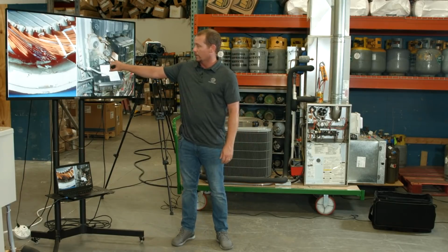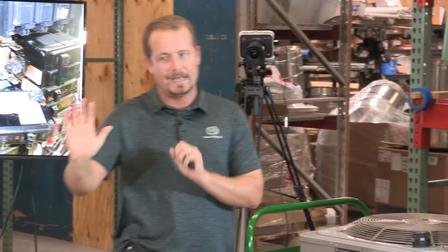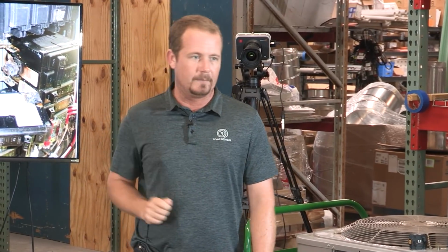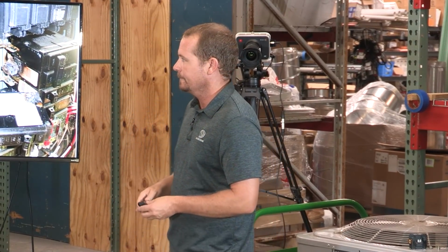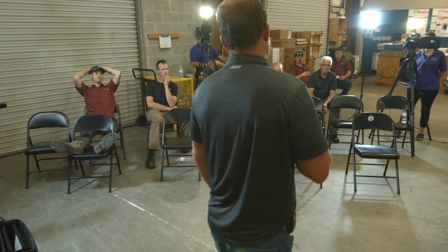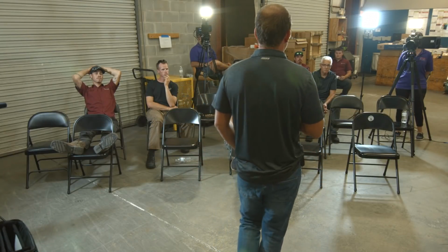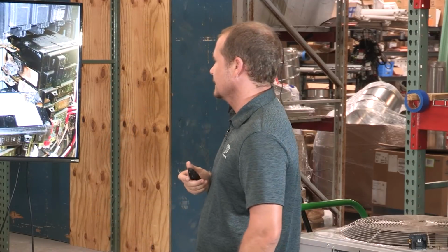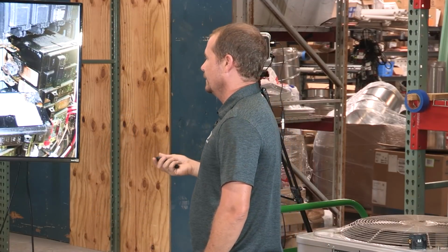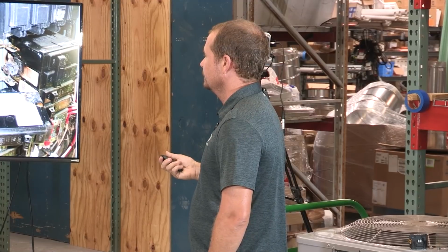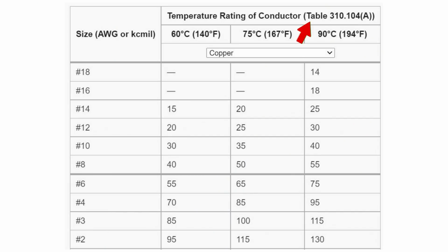In a lot of cases, it's a poor connection where it actually attaches to the bus. They may have never got it fully snapped in, and so it was just kind of sitting there bouncing on it over an extended period of time. Or if somebody removed the tabs to put quads in a panel that doesn't accept them. Yes, somebody removed the tabs to put quads in a panel that doesn't accept them. I would never know anybody who would do anything like that. Definitely not me.